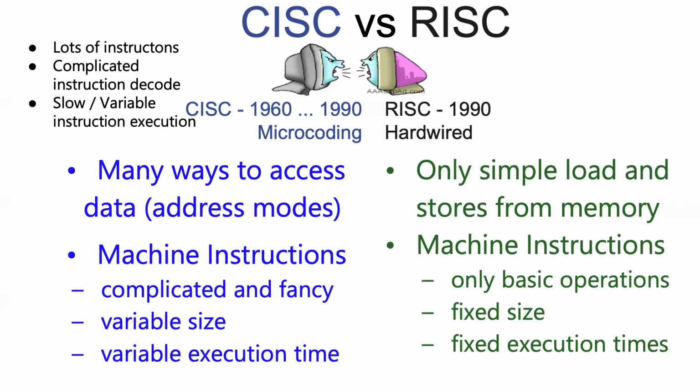So you saw this with the ARM processor. A RISC design might favor just a few addressing modes, just some simple ways to access memory, and an instruction set that includes as few operations as you can get by with, usually implemented with instructions that are all the same length and that all run at the same execution speed.